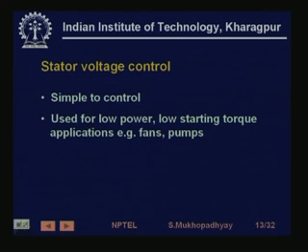It's typically fans and pumps, whose torque varies with the load. So initially you have low starting torques, and stator voltage control can be achieved in many ways.